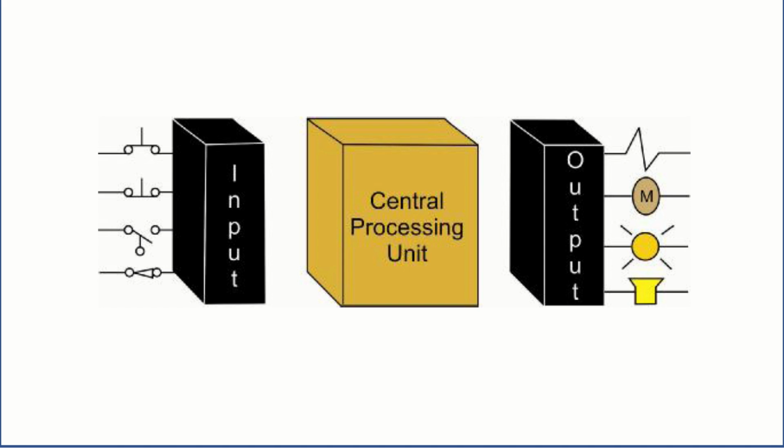Now you look at the PLC that you require, or you look at the PLC which is already installed at the site. See whether both the signal and the CPU are compatible or not. Once you are sure with all these aspects, then yes, you are free now to connect your sensor to the input terminal of the PLC.